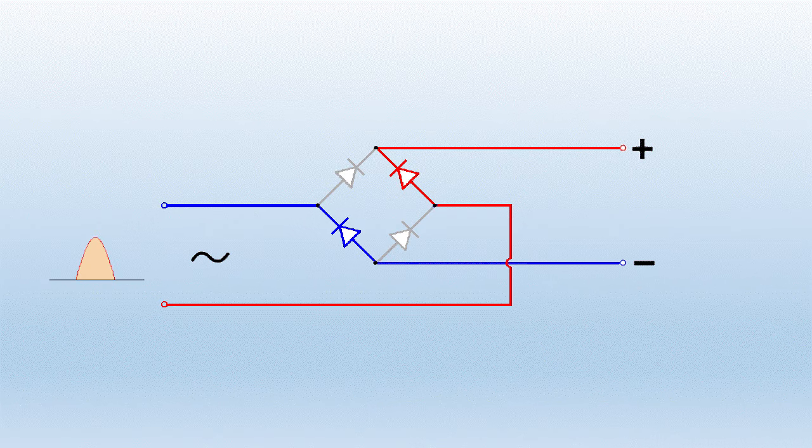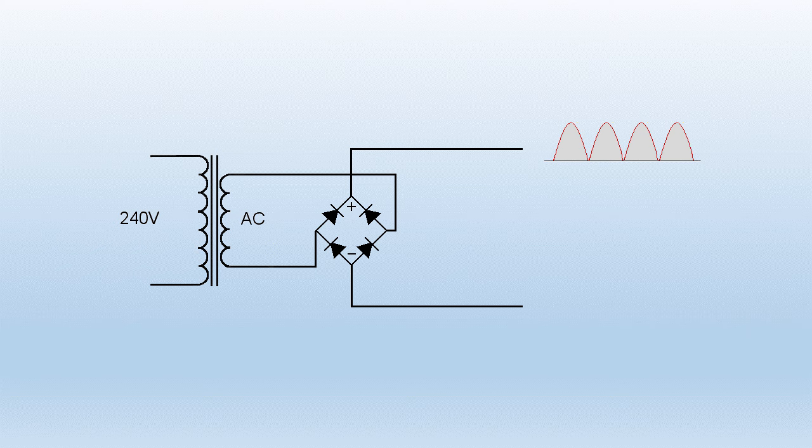And on the next half cycle, the top connection is now at zero volts and the bottom connection is at the higher voltage. So current will now flow from the top, the blue line, out through the load, back in the top of the red and back to the AC supply. In other words, both times of the cycle, current will flow through the load.